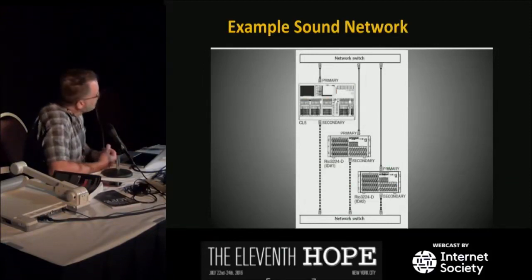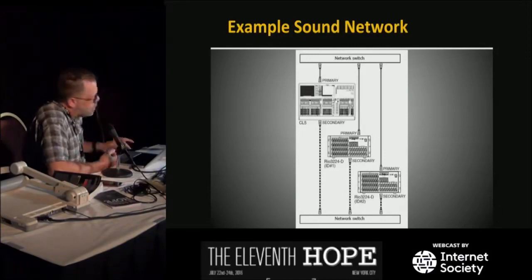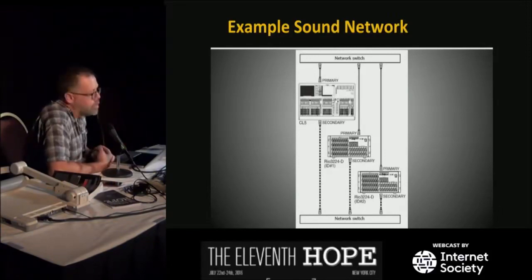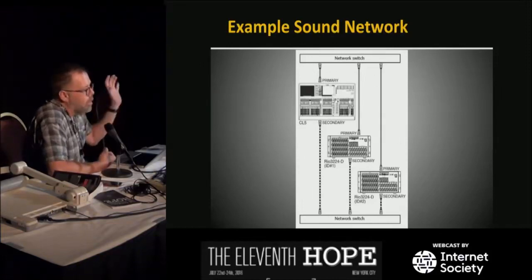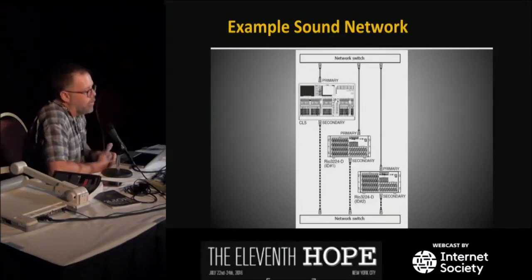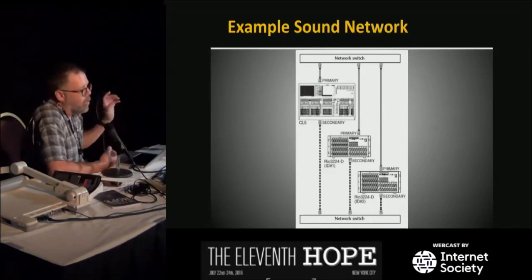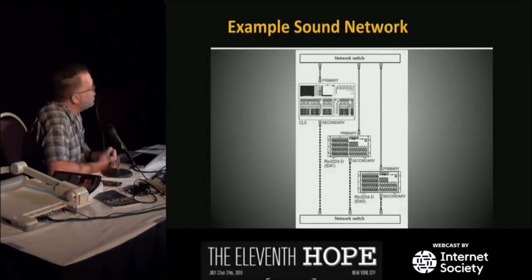We do, like I said, this system, when it's implemented in Yamaha's system, has a fully redundant network with 2 completely separate switches, and this thing works. I've tested this myself. If you just yank one of the plugs out, you won't even hear it. It won't even miss a sample. It's just rock solid with that. The only downside is in this system, no red light starts flashing, so you could lose a whole link and not know it. Then you lose a second one, you're screwed.